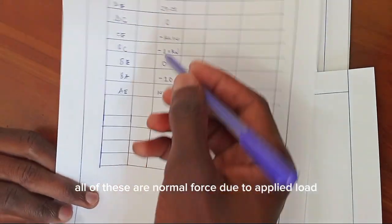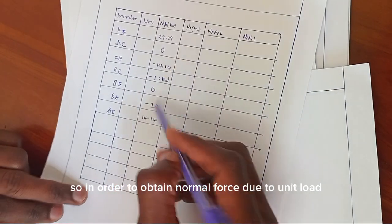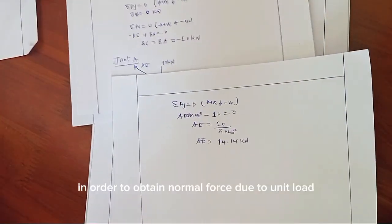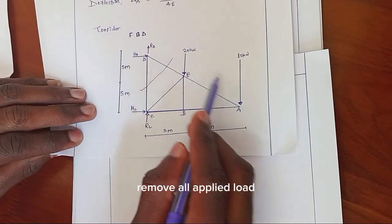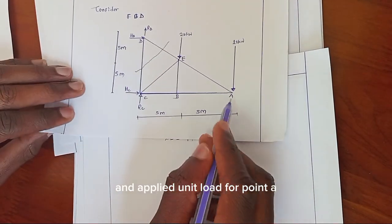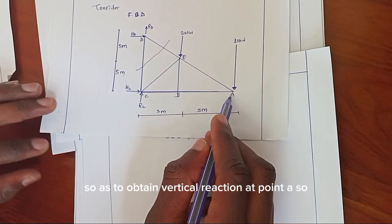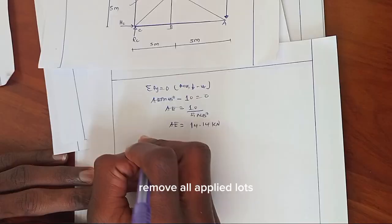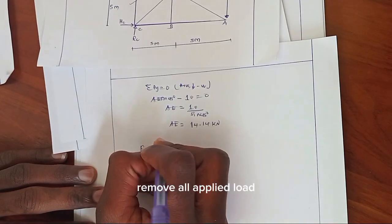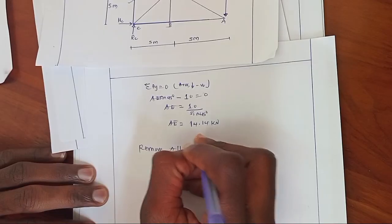Now, all of these are normal forces due to applied load. So, in order to obtain normal force due to unit load, we remove all applied load and apply a unit load at point A, so as to obtain the vertical reaction at point A. So, let's remove all applied loads